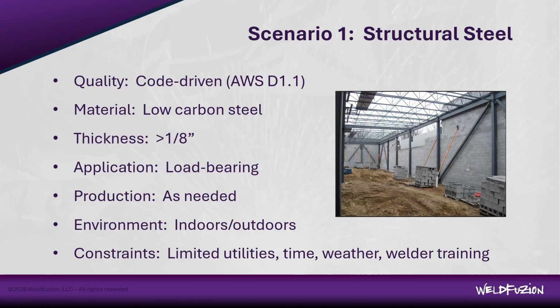Welds are made in a fab shop if they can be, so only short tie-ins and connections need to be made in the field. We're not welding the long beams. This helps to control costs because once you're out on the construction site, cost kind of goes out the window, right? You have to deal with what you have to deal with. There's too many uncontrollable variables. So anything we can do in a shop prior to sending it out to the field, we're going to do it. And that goes the same way with pipe welding and pipe shops. They have spool shops that weld up a lot of the pre-welded joints, and then very few welds need to be made in the field.